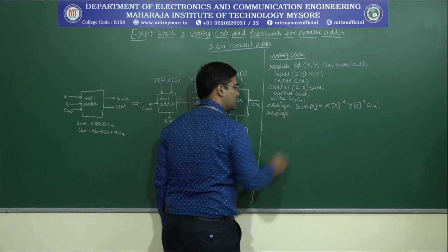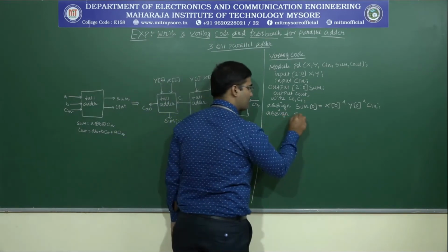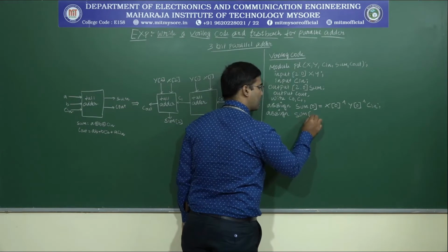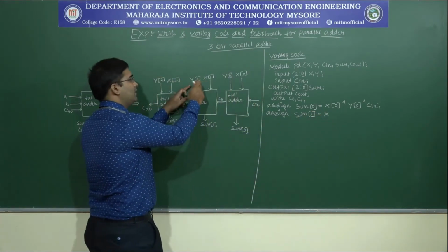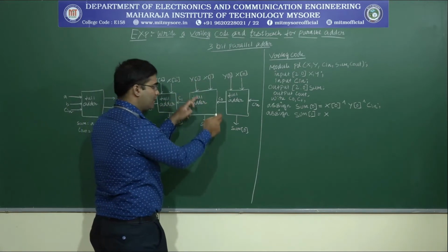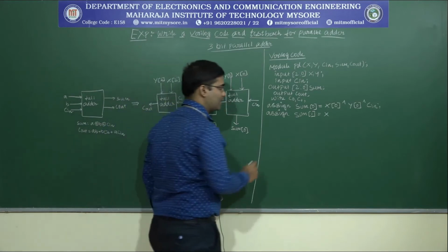Next we will use an assign statement for the sum S1, X1 XORed with Y1 XORed with C0.